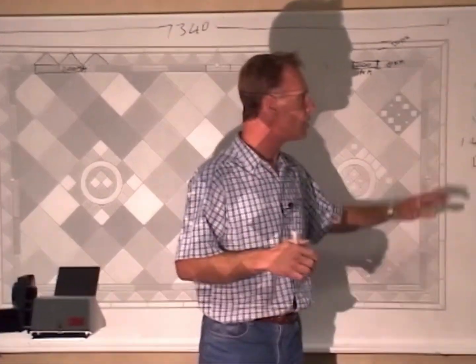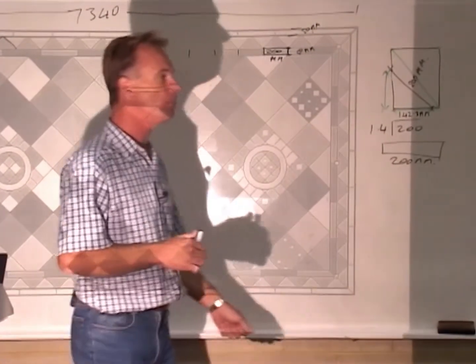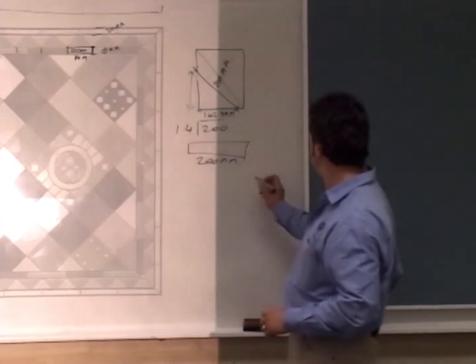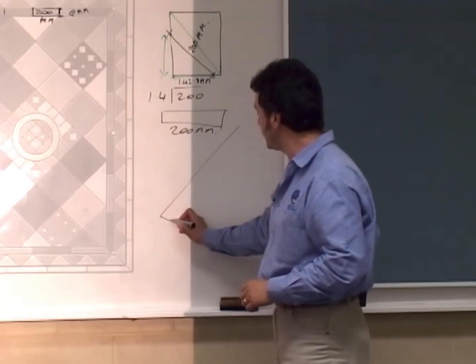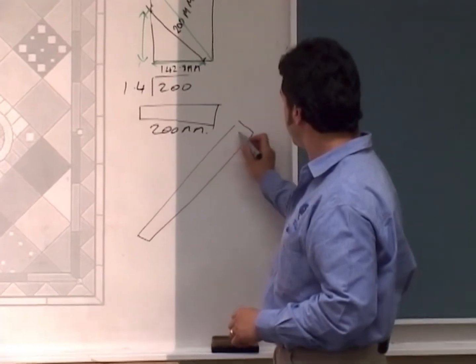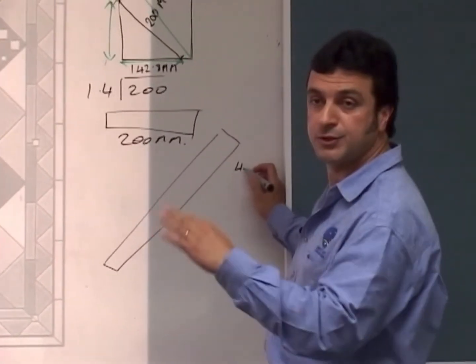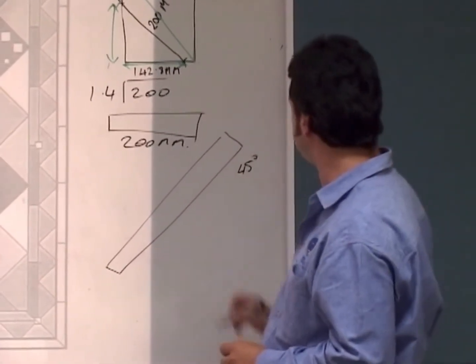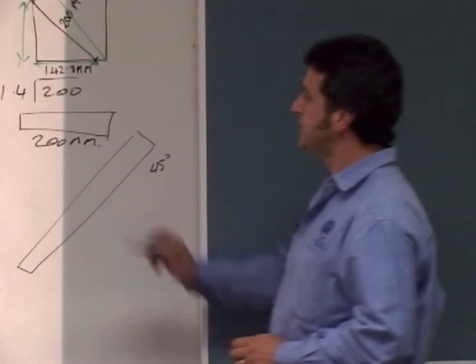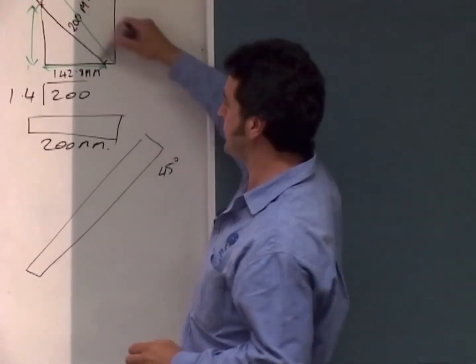Enzo, did you want to mention something along the lines of the cutting of that diagonal? Yeah, all the guys would be fairly familiar with their Sigma tile cutters, which have the swivel bar, which gets turned around and is set at a 45-degree angle, so it automatically produces the angle that's required.